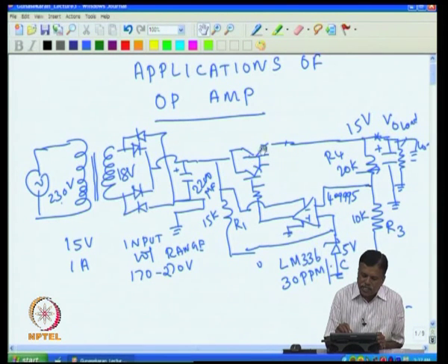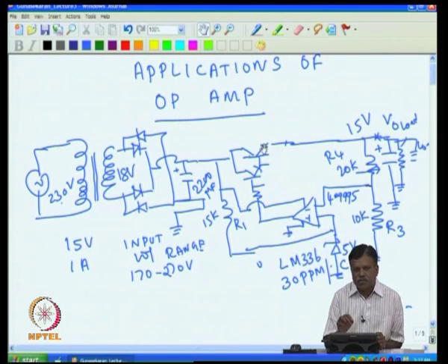Whereas, if I operate the transistor at 100 degree C, that is I limit the junction temperature 100 degree C, then this comes even more than 10,000 thermal cycles. If I operate at 80 degree, it goes even more than 1 lakh thermal cycles. So, it exponentially life increases if I reduce the temperature.